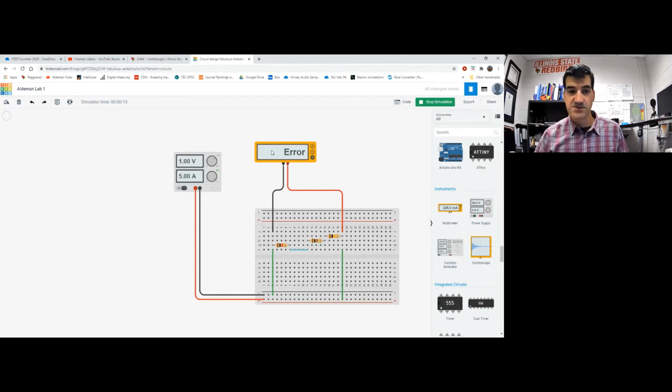You can't measure the resistance of a circuit while it's energized. Why? Because what you're doing in this path, in this circuit, you've created an alternate path for current. And that path is for current to flow through the measurement device. And if you're trying to measure resistance, you don't want that. You're trying to measure the resistance of these resistors.